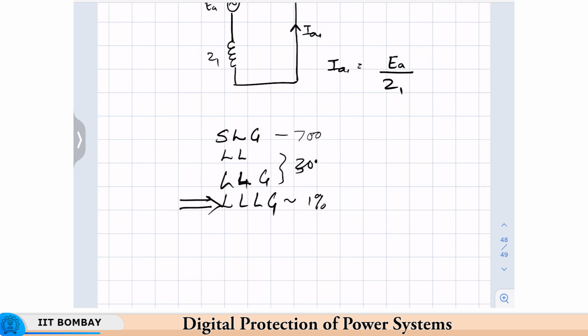Some earthing conductor is left and the line is closed, or some tool is left on the bus bars by the staff or something like that. Whereas single line to ground or double line faults occur more frequently. This could occur due to something touching the conductor, or some tree touching the conductor, something like that. So, the probability of that occurring is much more.